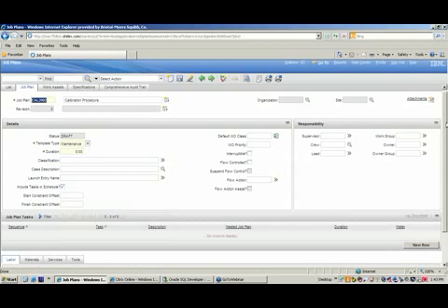But your typical task might say step 1 is follow manufacturer's recommendation for calibration. Or it might say refer to your standard operating procedure for how to do the calibration. That's all you need. You just need a couple of steps in there to tell you to go refer to something else. And then in the Work Assets tab, where Hank did that association, you could literally just associate every instrument you have with all of the specific data sheets that it needs. And once you do that, once you create a work order for the specific asset, it will know based on the job plan which data sheet to associate.